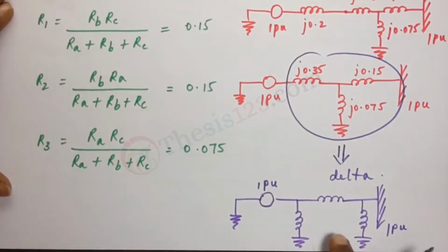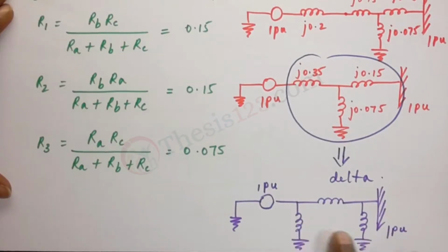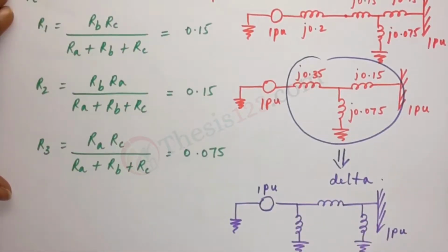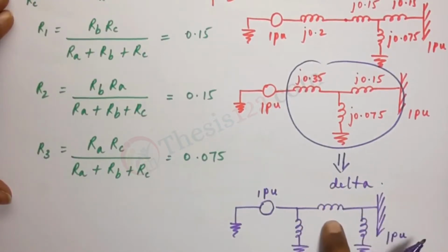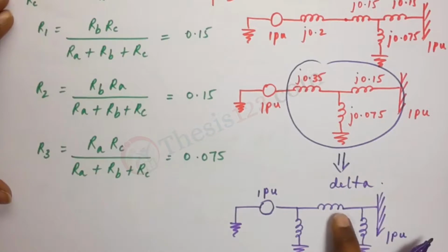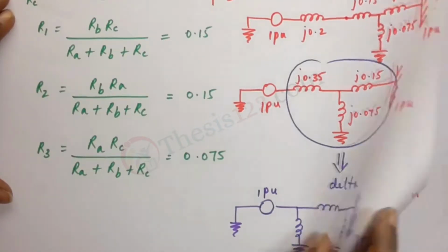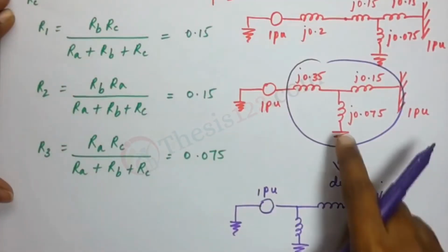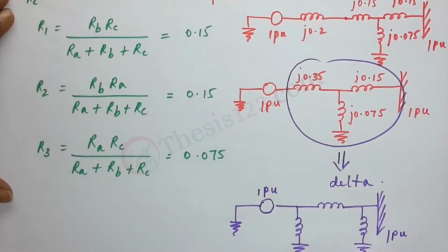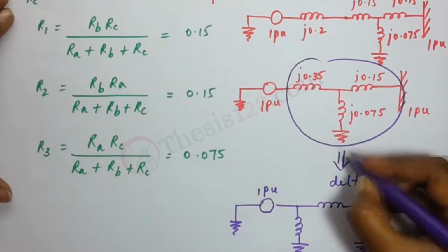This is because when a fault occurs, the second line would be grounded immediately. So the remaining impedance is what we have to use to calculate the maximum power that passes through that particular point. Since we don't have that in the first equivalent circuit, we have to try and resolve it as much as possible in order to get it into pi form. That's the ultimate aim here.